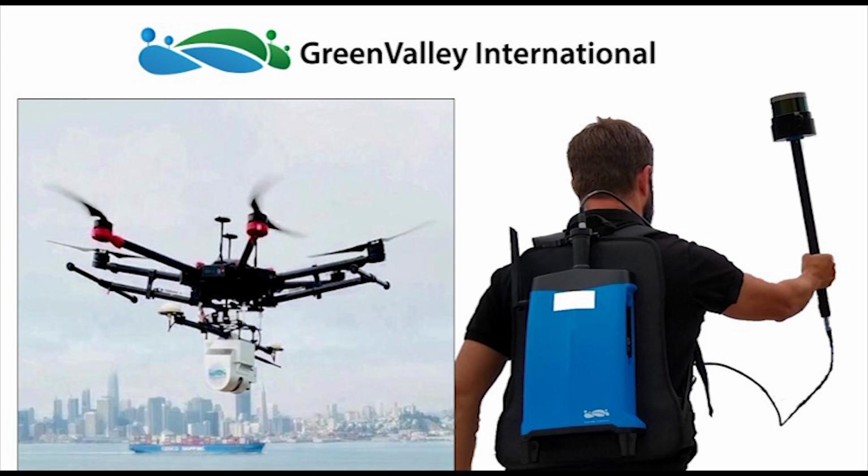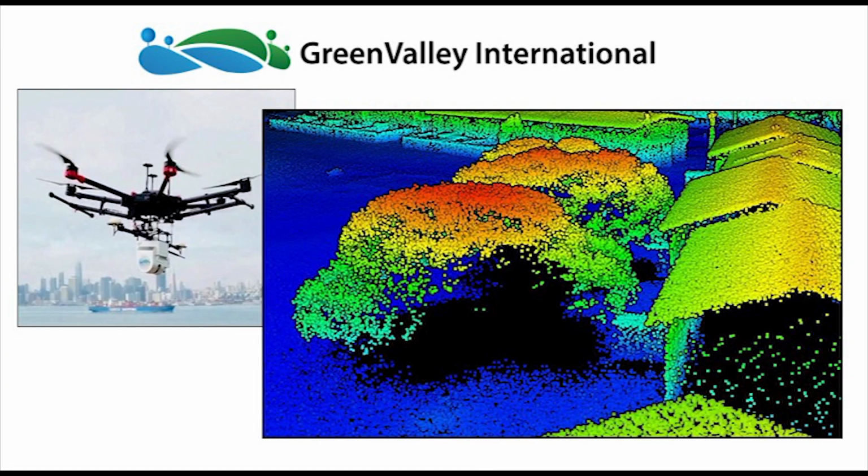when I got back to the office that the UAV LiDAR data collected the areas on the tops of the buildings and the canopies of the trees extremely well, while it missed some of the sections of the point cloud that represented the facades of buildings and the undersides of trees.